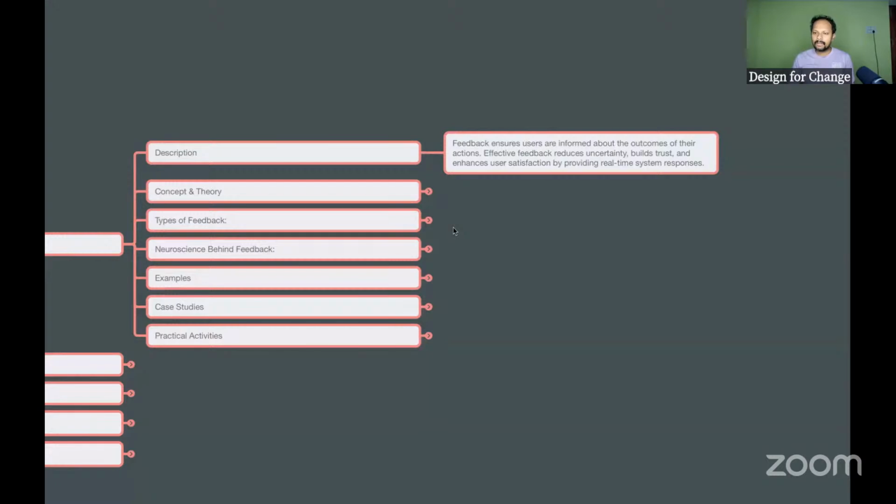So that is where you need to take multiple approaches. Why don't you flash an LED screen? Why don't you put a color on top of it along with the additional alarm screen? Why don't you increase the sound for a high priority alarm and keep a low sound for a low priority alarm? For a critical thing, like if the heartbeat goes down, that's a very bad symptom, so the red color should pop out and the sound should be high. So we created an LED panel around our ventilator, because the doctor gets super confused.